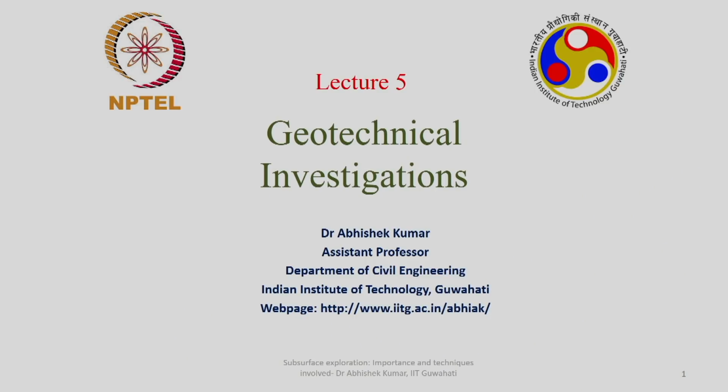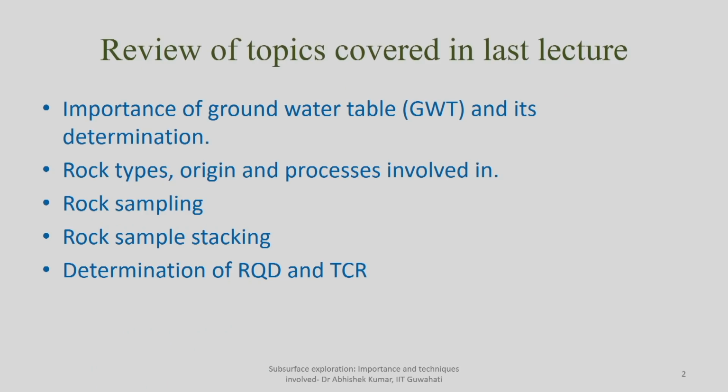So before going further to today's class, let's review the topics we had covered in the last class. We tried to understand the importance of the groundwater table when we go for subsurface exploration: how the groundwater table can help you in understanding the soil type and foundation type required, how it can help you in planning for detailed investigation, exploration, even laying of the foundation, how it can help you in dewatering if it is required, and further in ensuring the safety of the adjoining structures as well.